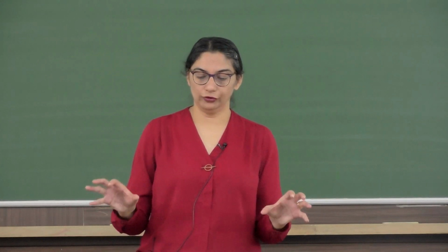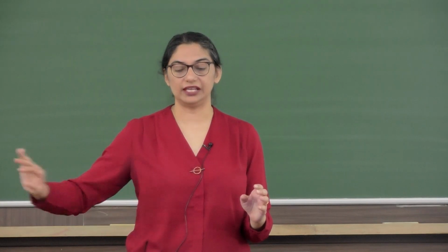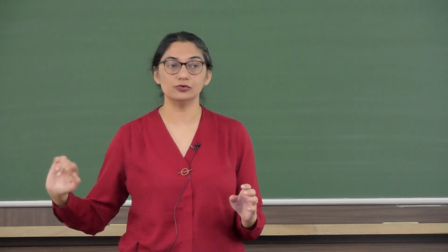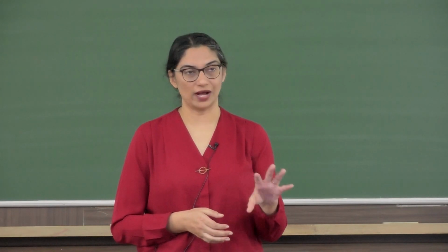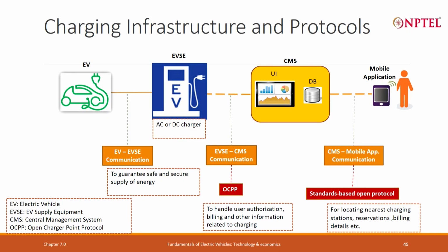Now, if we see overall, we have talked about two different standards. So, we will leave aside CMS and the user, because that is something that the operator would define as the app interface. The different standards are EV to EVSE, one set of standard, and second standard is EVSE to CMS. EVSE to CMS, since it is only one standard that is defined, there is no conflict. We just pick it up that all different chargers have to communicate in such and such language. Standard is nothing but a language, right? Set of protocols or rules that they have to follow, the message and the structuring that they need to follow, and they need to communicate to CMS. So, there is no conflict on that part also.